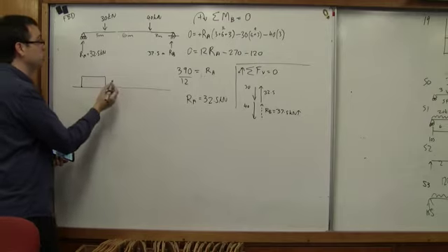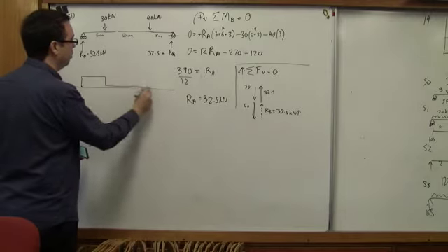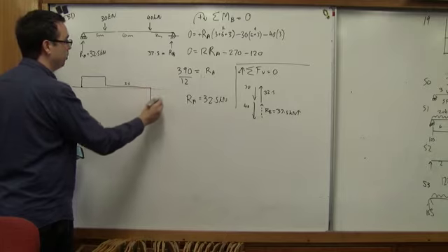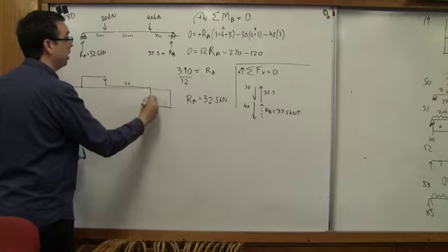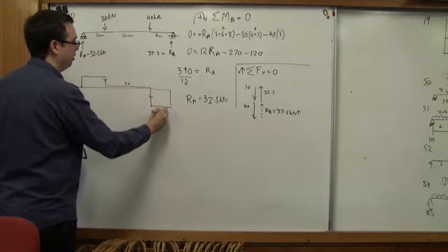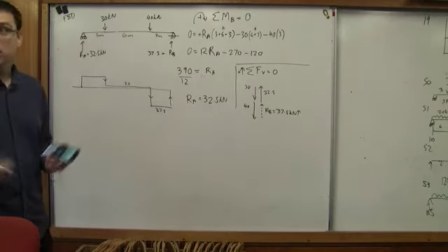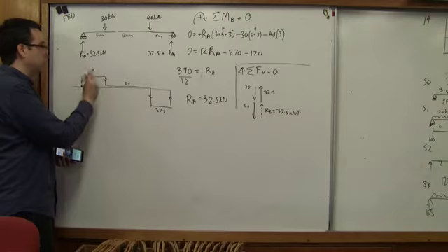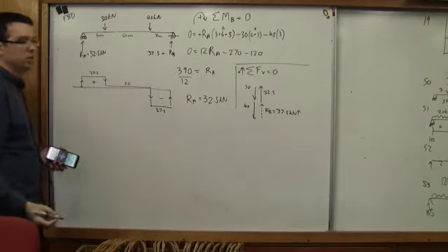So now it was at 2.5. It went along at 2.5 for quite a long time. But then something scary came along and it went down again, and now it was at minus 37.5. But luckily, at the end, reaction B came along and returned everything back to the way things were at the start. So that's what the shear force diagram looks like. This is a positive area, these ones are negative areas.